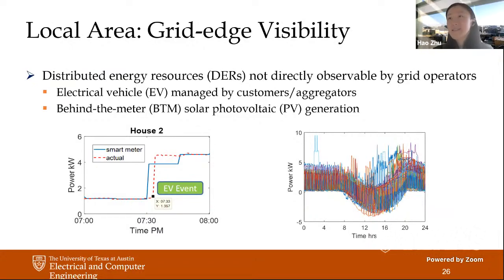So that's why at the beginning of electrification, we liked more and more systems interconnected together, more and more generators interconnected together. But then this interconnection brings down the cost, makes the system more reliable, but also could lead to some resilience concerns. So if there is a local failure, because of this interconnection, it would affect other places as well. So I think going forward, there needs to be a good balance between this interconnected grid to have cheap, efficient, and carbon-free generation from anywhere in the system.